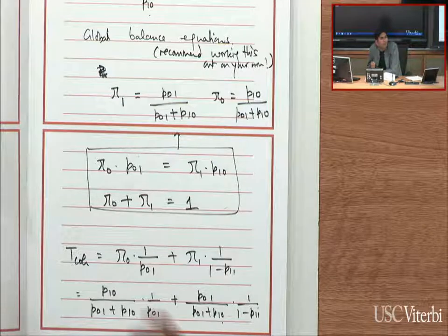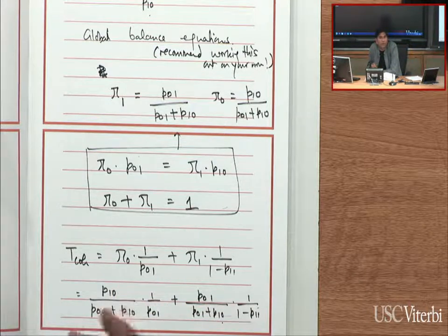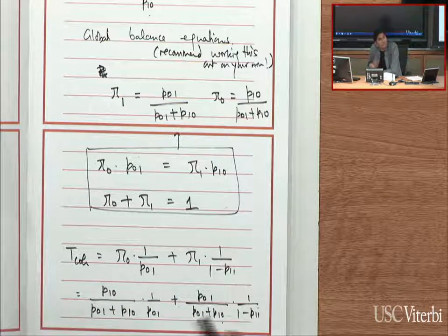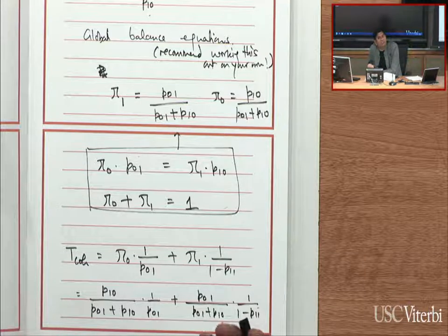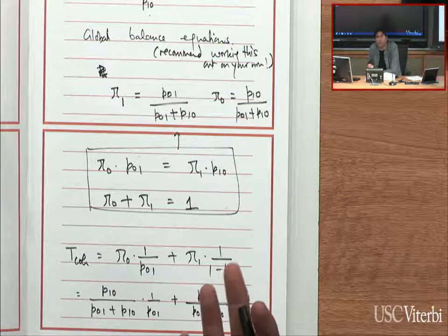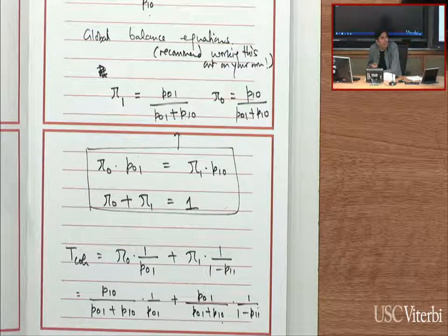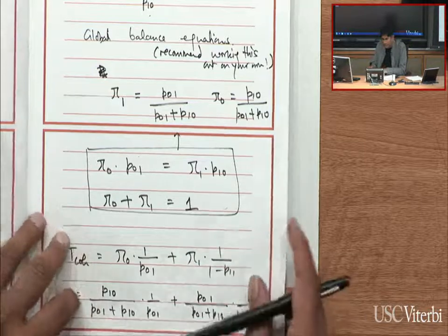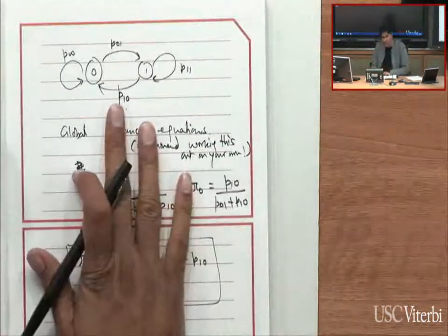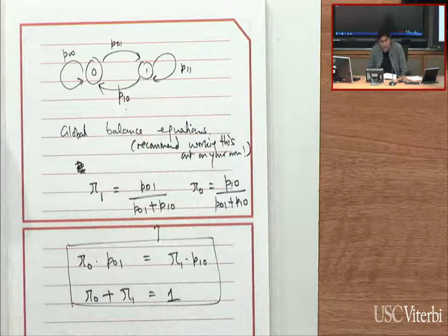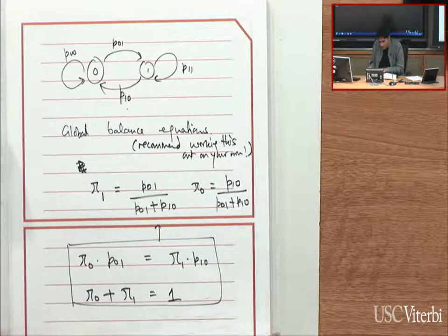In the meantime, if you were to send a packet, because you already know from your understanding of the model that the channel is likely to stay bad, you're just wasting the transmissions. You might be wasting power, you might be causing more interference for other nodes. So by modeling the temporal dynamics in the link, you can make your links more efficient. So that's an example of how we can use it. We'll come back to this model and this particular link adaptation question again.